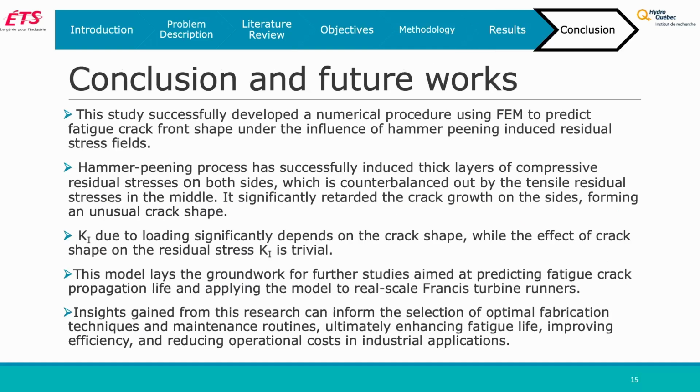To summarize my work, in this study we were able to successfully develop a numerical procedure that was able to predict the crack front shape. Of course, there were some differences between the results of the simulation and experiments, and that could be due to the scattered nature of the fatigue problem, and also some assumptions that I made. For example, I didn't consider the residual stress redistribution and relaxation due to the fatigue growth.